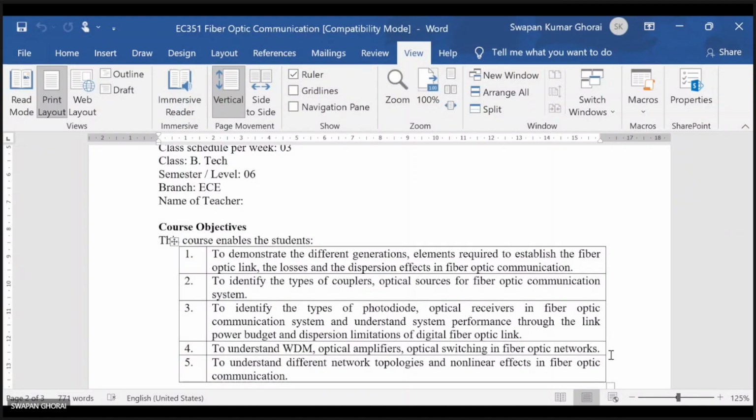We can amplify it by converting the optical signal to the electrical domain, amplifying it with conventional amplifiers, and then converting it again from electrical to optical. When you do these conversions, noise will be incorporated, and that will degrade the signal to noise ratio. So instead, if you perform these amplifications in the optical domain, you can have far better results.